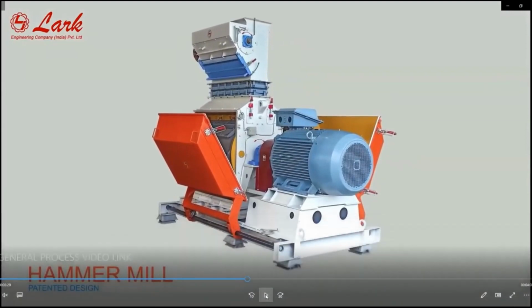The main feature a hammer mill should have is the gap adjustment between the hammer tip and the screen, because for fine grinding we need less gap between the hammer tip and screen. For coarser grinding, we need more gap between the hammer and the screen. So there should be an optimum gap adjustment mechanism in the hammer mill to control the grinding process and to increase the efficiency of the hammer mill.